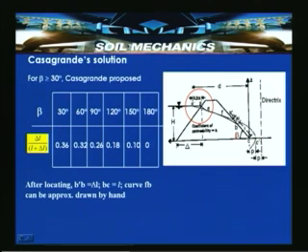So, after locating B dash B equal to delta L and BC equal to L, the curve FB can be approximated by drawing by hand. So, by adopting the procedure, that is from the upstream face setting a distance 0.3 times delta, and maintaining orthogonality here and drawing a free curve for joining FB, we can construct this phreatic surface. Once this phreatic surface is obtained, we can use this concept to construct the flow net for determining the rate of seepage through an earth dam.